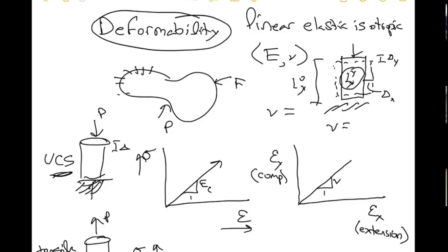So the Poisson ratio is minus the strain in the X over the strain in the Y. If you apply this much, 1 unit, and it bulges out 0.2 units, then the Poisson ratio is 0.2 because they're opposite directions. You squeeze it, it's a negative value, and it extends, that's a positive value. You get a negative ratio, but then you switch the sign. That's why there's a minus sign here, because you want this to come out positive. It's more convenient. Okay.